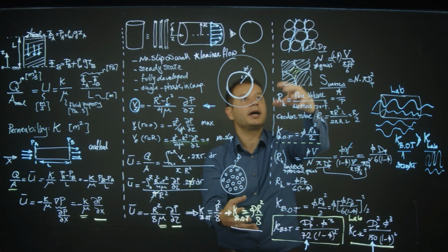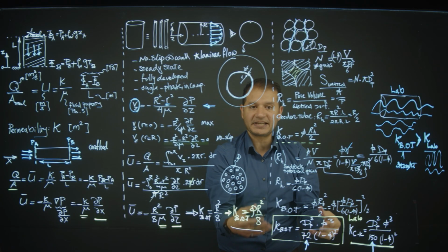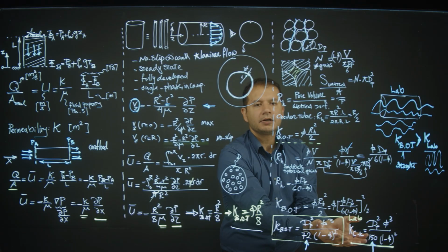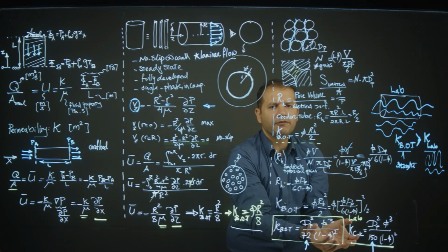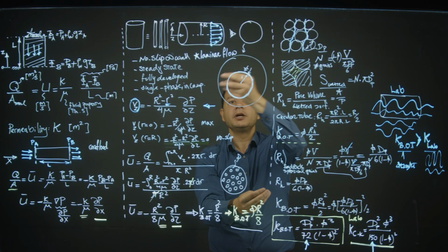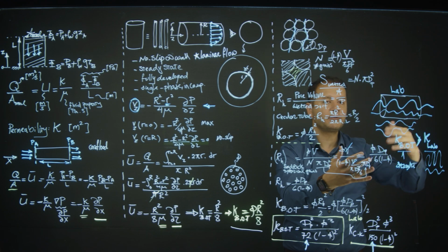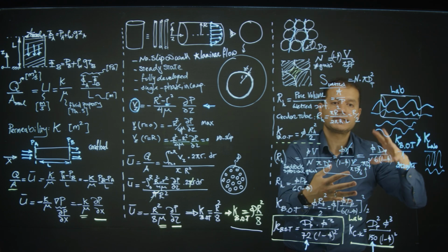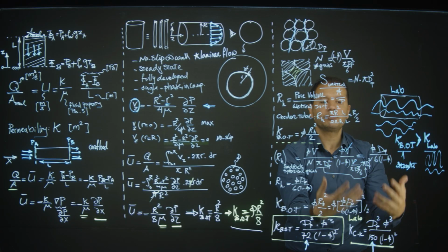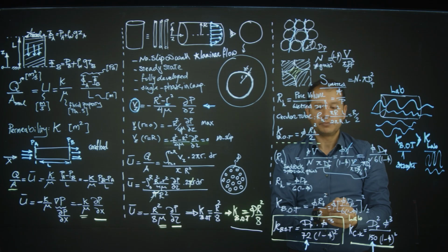And then by definition of hydraulic radius, we can find the permeability for a sandpack, which is at the end almost 2.5 times bigger than what we find in real experiments. The reason is we assume flow is straight, while in reality, flow in rocks or porous samples is very twisted and tortuous. Tortuosity is the reason behind the lab permeability being smaller than the bundle of tube theory.